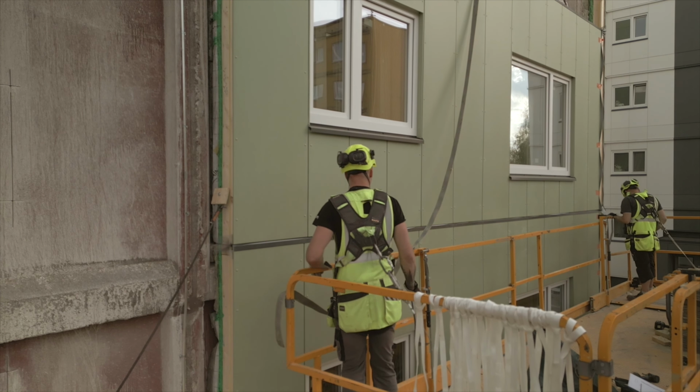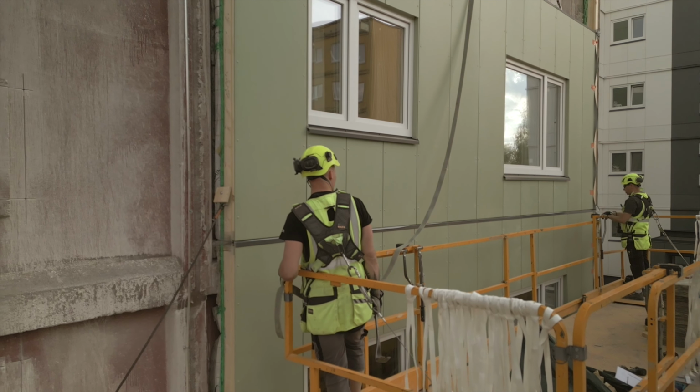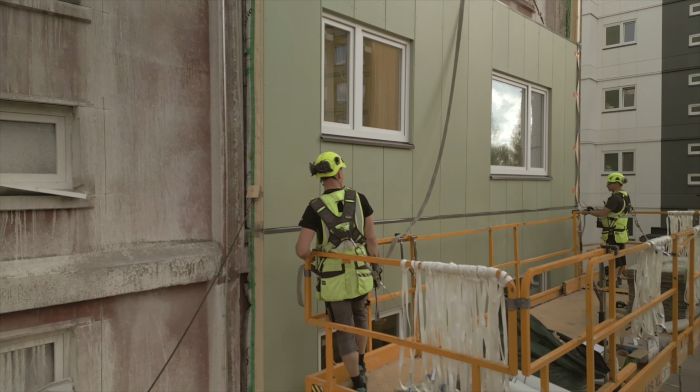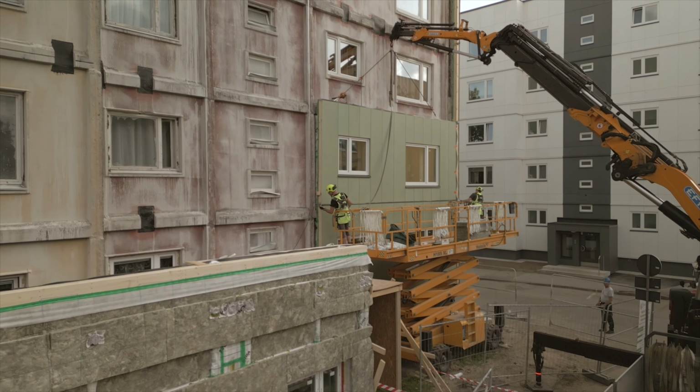The room air becomes more humid and the amount of carbon dioxide increases. Therefore, the ventilation system is the main difference between typical external wall elements and facade elements used for renovation, and its purpose is to reduce the risk of moisture accumulation and improve the building's indoor environment after renovation.